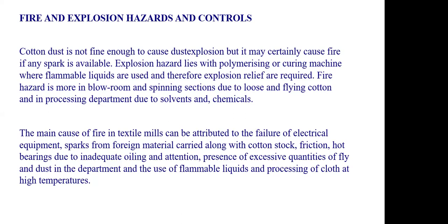So here what will happen? There are many causes. If your equipment is not maintained well, if proper preventive maintenance is not done, or lubrication is not done properly, then what will happen? It leads to friction in unlubricated parts. So there, what will happen? It will create a spark.